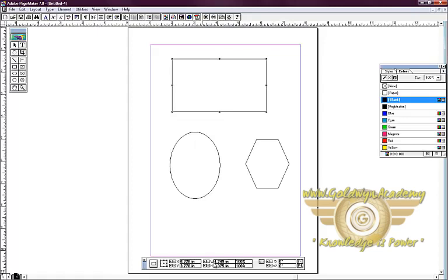One more interesting feature about the control palette is the tilt of the rectangle. You can actually tilt the rectangle as you want without going and selecting the selection handles. These arrows tell us how to actually modify and tilt the rectangle. If I want to tilt it to the right hand side, we have to go and click the down arrow. The corresponding degrees will appear.